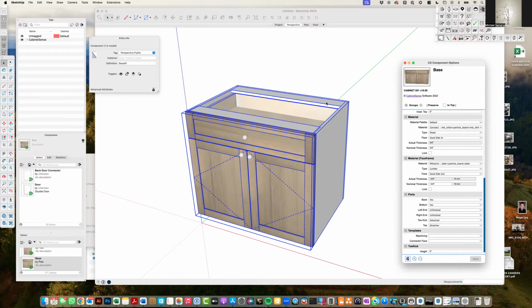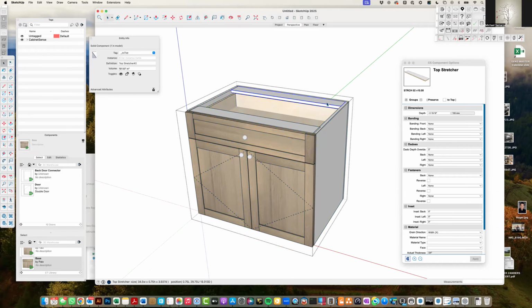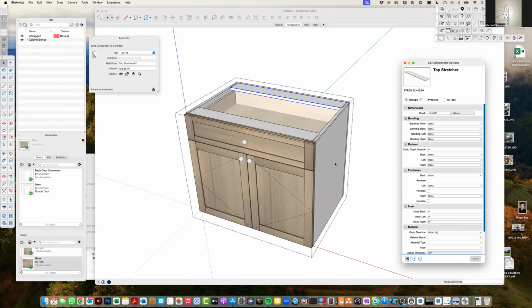Okay, back one also. So I'm going to go back here and dado left dado and right dado, just because that way the side panels are all the same, whether we're doing a stretcher top or a full top. That makes sense, it's easier to manufacture them in batches.